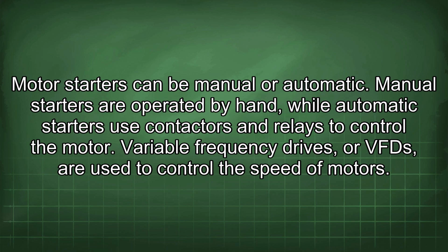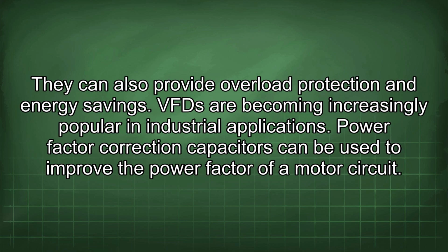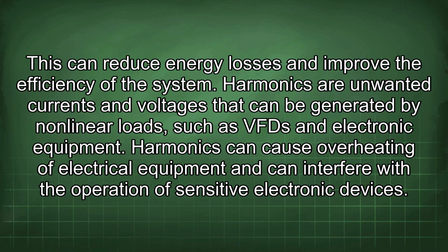Variable frequency drives, or VFDs, are used to control the speed of motors. They can also provide overload protection and energy savings. VFDs are becoming increasingly popular in industrial applications. Power factor correction capacitors can be used to improve the power factor of a motor circuit. This can reduce energy losses and improve the efficiency of the system.